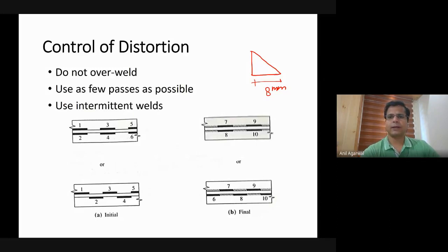And what I find out is that with a single pass of my electrode, and that electrode size also depends on the size of the weld, the base metal, or the machine capacity, I can make a certain size weld. So what I'm planning, let's say, is to do this. One pass will be this. Then I will come back again and do this pass.